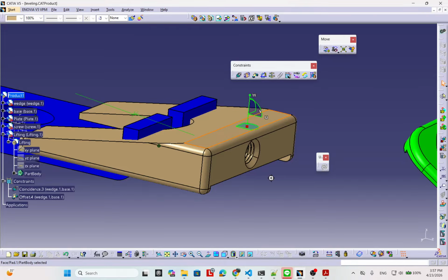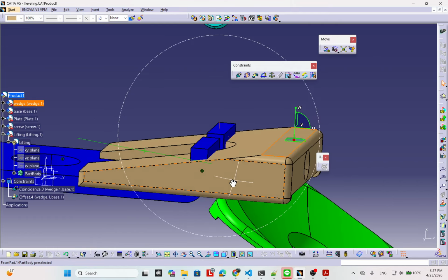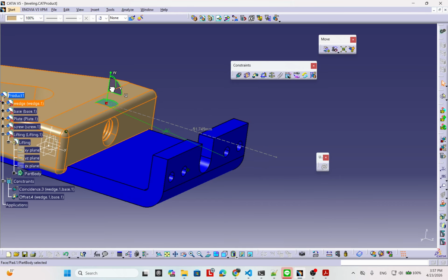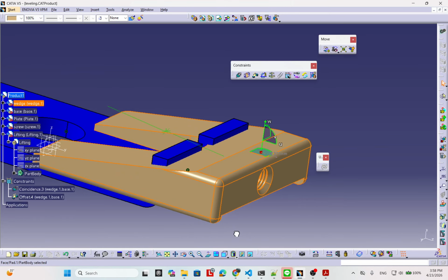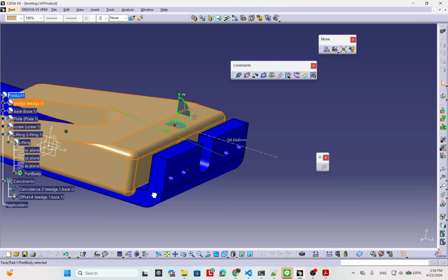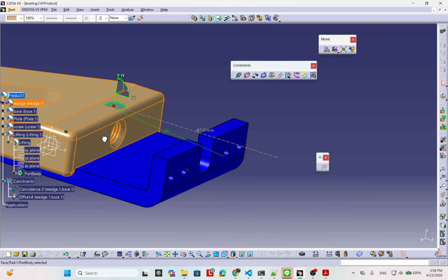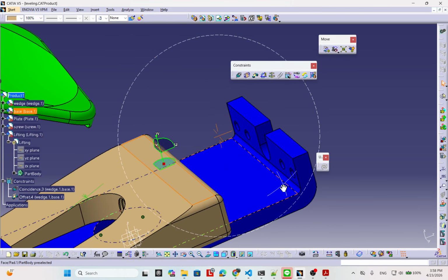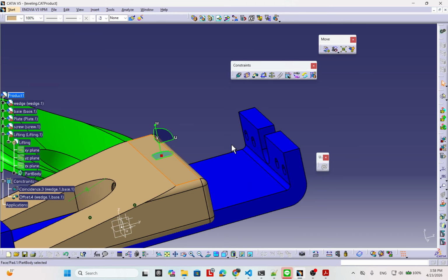Okay, then you cannot update, because why? It never knows about this, because right now this has already broken the constraint, and the program doesn't know because you never created the constraint along your axis, the y-axis.